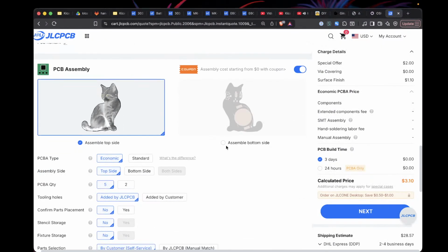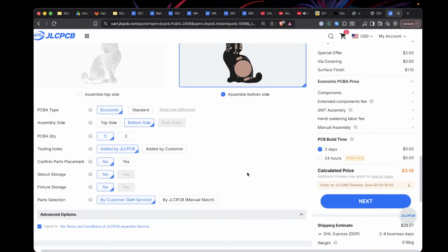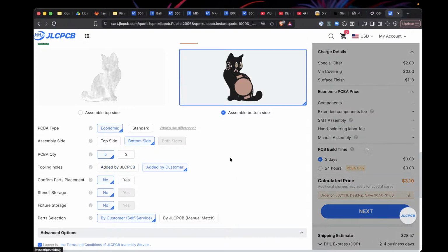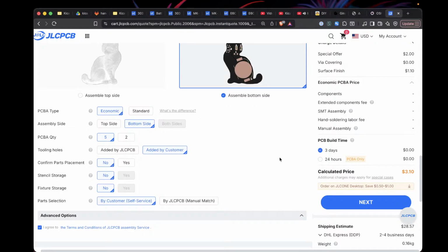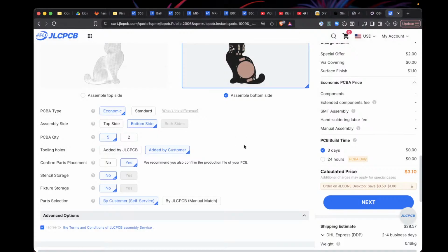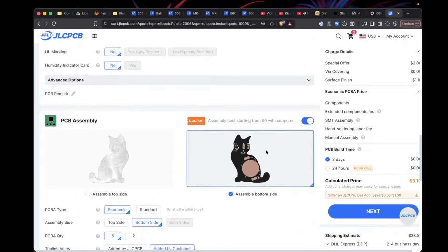Yes, and in fact, there's a program called EasyEDA to KiCad, which is a Python script. Basically, if you have all the part numbers, like these LCSC part numbers, it will populate footprints and things that are exactly the parts that you can use. Okay. And once you're doing this, you'll go on JLC PCB and look at their parts library and see what kinds of parts they have. They have a lot of stuff that you can use.